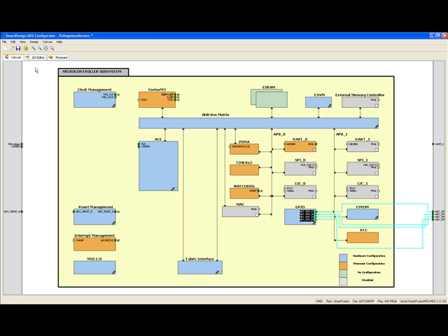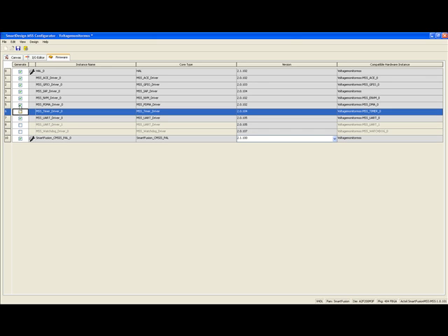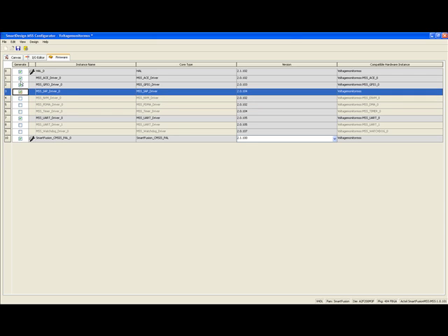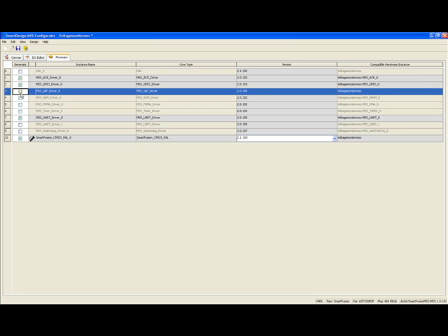Now, click the Firmware tab at the top of the SmartDesign MSS configurator. The Firmware tab provides a view of all firmware that should or could be required for the design. For this design, you do not need the Watchdog, Timer, NVM, PDMA, HAL, or UART1 drivers, so they can all be unchecked. Note that if the core type names are displayed with italicized font in the firmware catalog, this means that the firmware cores have not been downloaded from the Actel IP repository to your local drive. If you have an internet connection, you can right-click on the core type name and select to download the core. By default, the IP and firmware cores are downloaded into an Actel folder on your C drive.